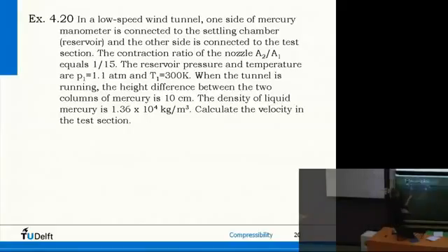Then, if these pressures are not the same, with mercury here, we will get a difference in height, right? Because on both sides we have pressures pushing, so we have a force. The force is P1 times A. Here we have P2 times A. And if they're not equal, then thinking about the balance at this location, the total force here is this P2 at this location, A, plus the force from the mercury column.